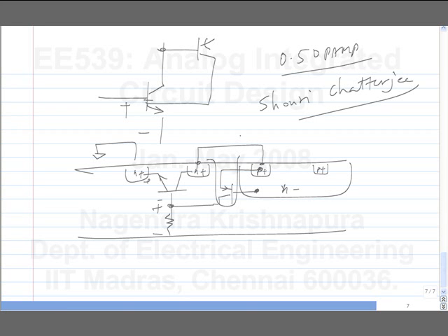No, if you have 0.5 volt supply, that's it. You are limited to that one. So, in fact, see the half volt circuits that have been built so far, they are not very power efficient. They take lots of current. So what the op-amp you can make with 1.8 volts, you compare it to half a volt, the total power consumed by half a volt circuit is a lot more. That's because you need lots of other bias branches and other things. And with a half volt supply, you can only expect a swing of the order of half a volt. Okay. So that is always a problem.